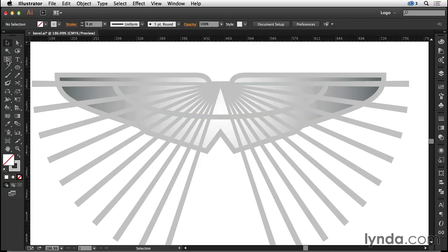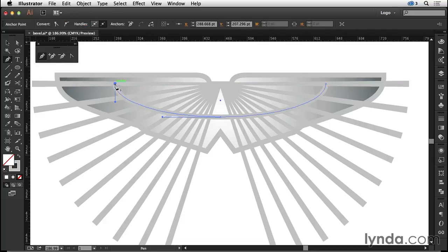Now switch to the pen tool, come and pick up that open path and connect that to the outside shape. As I do so, I'm going to click and drag. And I didn't quite get that right. I'm going to have to come and move that down in a minute, but I'll do the same on the other side. First of all, deselect the stroke, click on the open endpoint, and then click and drag.